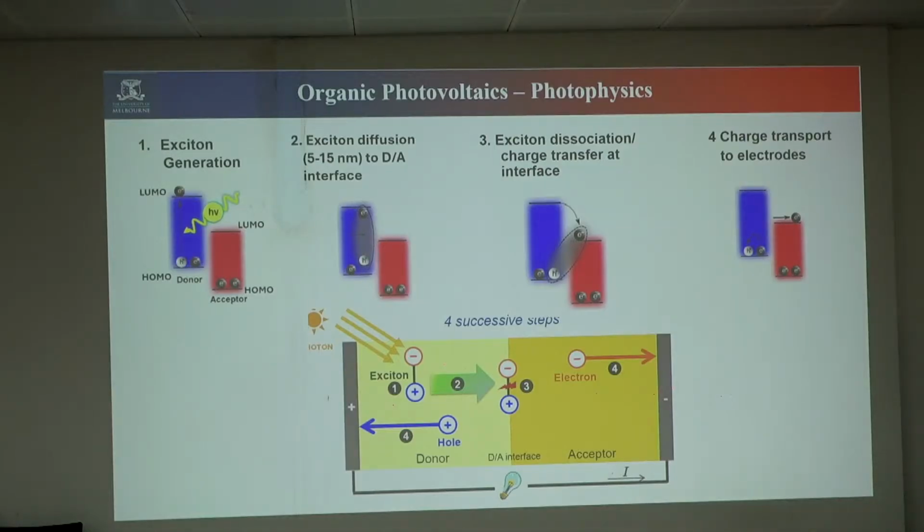The inverse of this process is called an OLED. We will see the other things on the last day, the light emitting device, where the exciton is generated from light and we separate it out. In the opposite way, we inject the charges, recombine them, and get light. Maybe you can easily understand. If you understand this one, that is very easy. You need to understand that exciton means a bound hole and electron. That's the meaning.